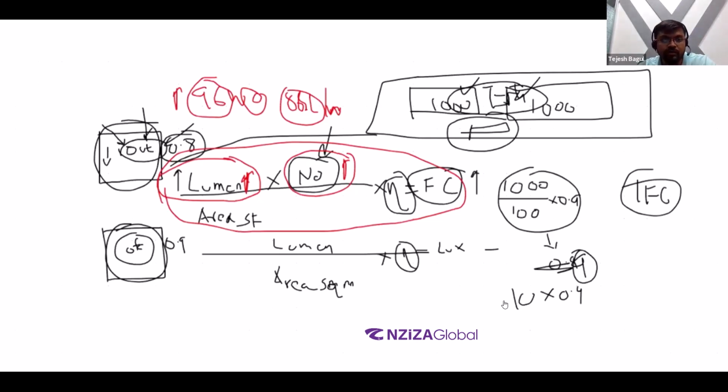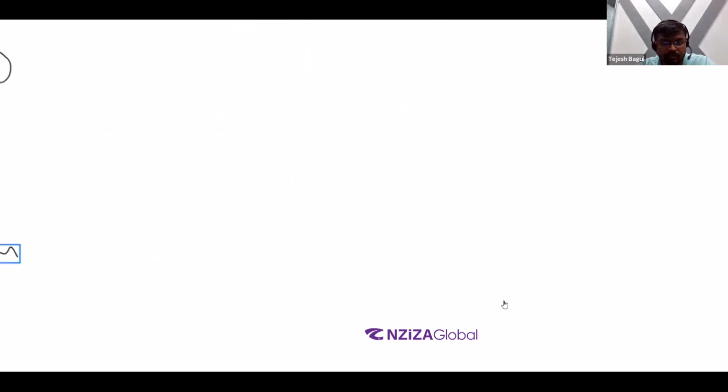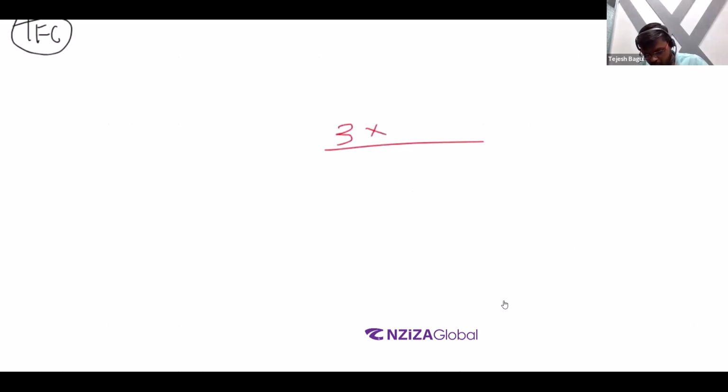But moving forward, regarding the calculation that we had for our given area, we had a total of 3 luminaires. We had calculated the lumen package at a total of 8549 lumens.